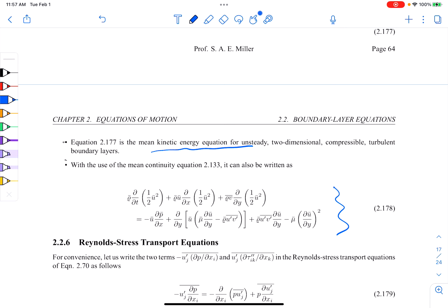So what does this track? You can see this is tracking u bar squared. And we've dropped the v term, which is good because we decoupled it in the time domain term. So if you use a marching technique with like fourth order Runge-Kutta, it's greatly simplified things. So that's basically the Reynolds-stress trace tensor.